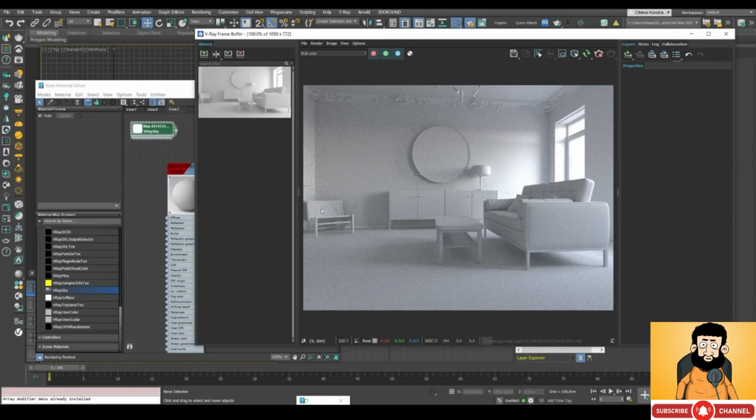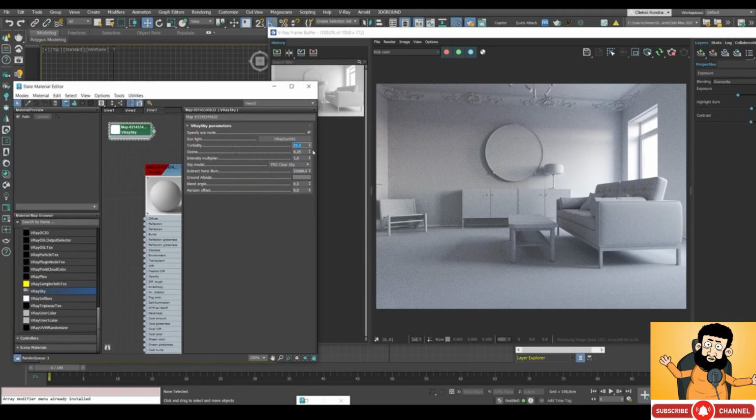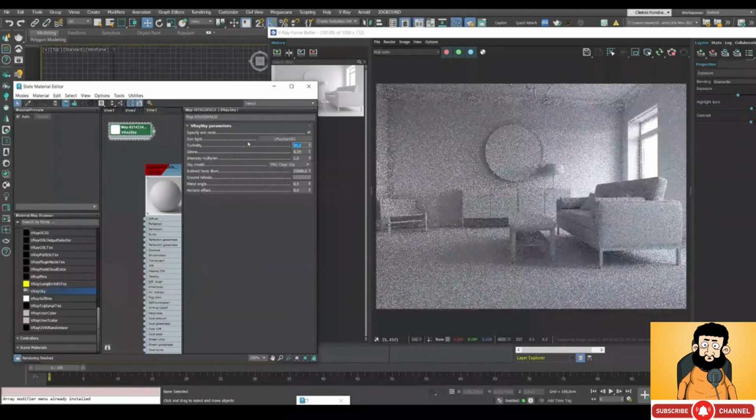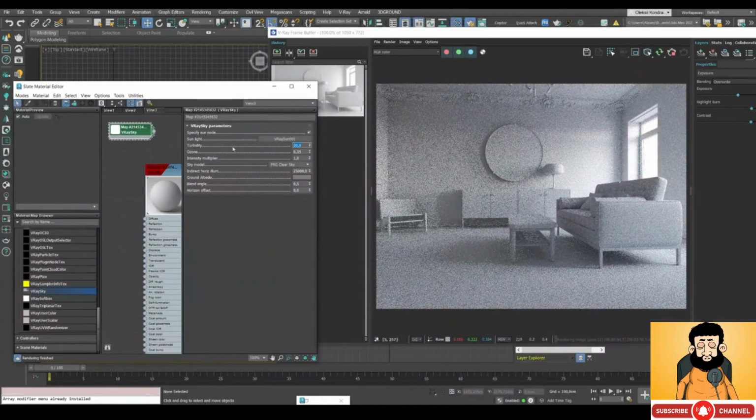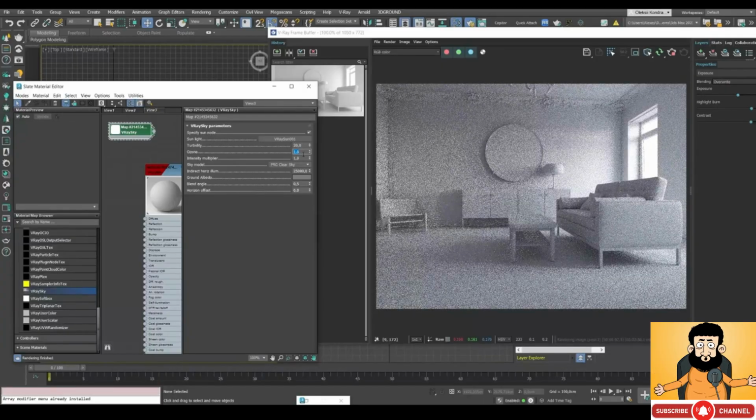Right now our scene is too white, so we need to do some post-correction. Plus we have strong highlights on the window frames. So we add the exposure settings and lower highlight burn. At the same time we increase the contrast a little bit, and this is what we've got as a result. Let's put turbidity to 20 or 30. Doesn't affect the light too much. Ozone also affects the shade of light, but not in any major way. So you can probably skip it altogether.